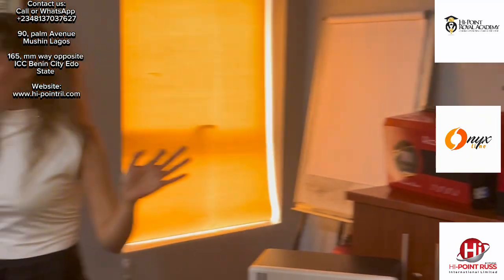It's not about the products. If you want to connect BMS between an inverter and a battery, and you notice that the inverter is not communicating with the BMS, what will you do? My advice as an engineer: do not only bring the user manual for the battery, bring the user manual for the inverter, any battery and any inverter, and open the pin section.